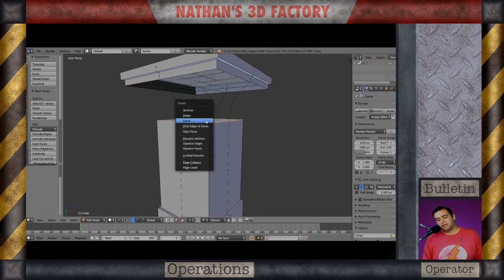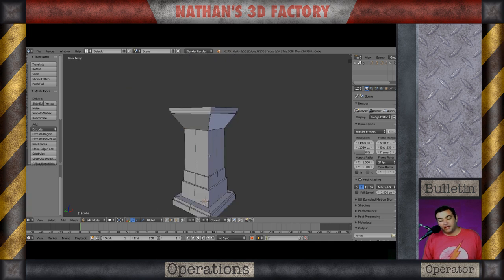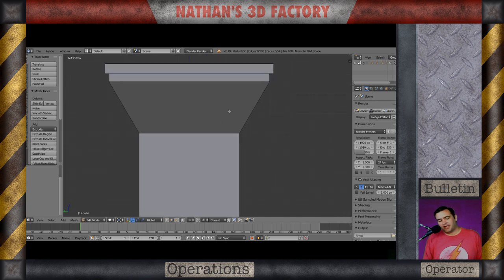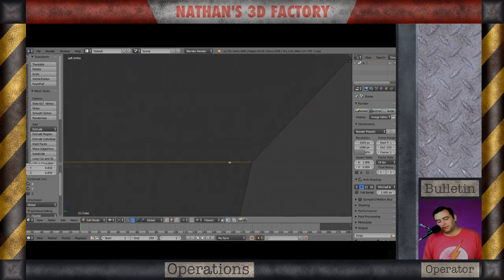Alright, step 3, I'm going to delete that face. I'm going to do the same thing for the other one. And now I'm going to take those edge loops and I'm going to bridge them. There. Now, on this object, I have this so that there's a curve on it. And what I'm doing is I'm adding some loop cuts here. I'm going to scale them inward. I'm going to make sure not to include the z-axis as I'm doing these scales.